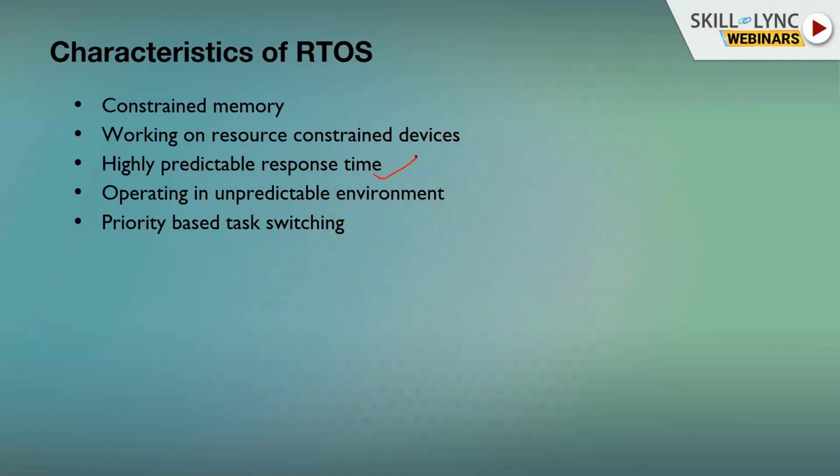Okay, because of the highly efficient processor, we see as if only one task is running in the system, whereas there will be multiple tasks running in the system. But in a real-time operating system, each event is going to be deterministic in nature. It is always known that this is going to run for only this amount of time. So that is significant in a real-time operating system, and based on that, scheduling algorithms are prepared.